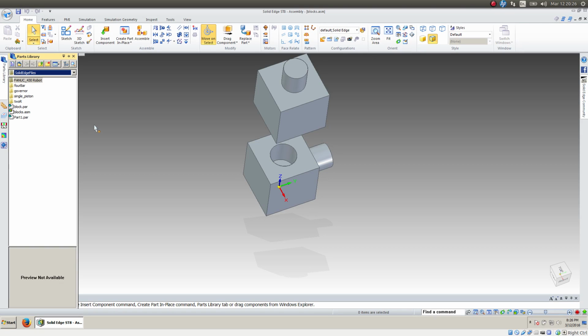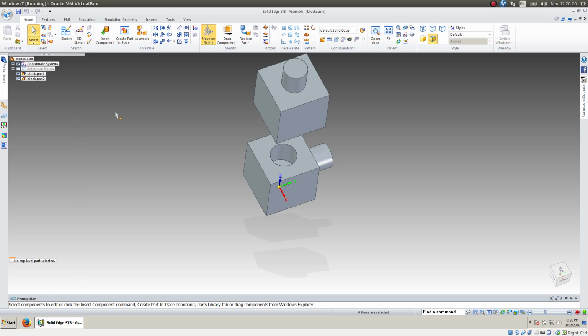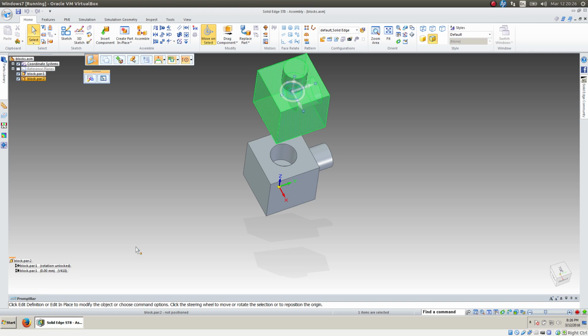In dynamic design or motion, it's possible to have somewhat adaptive inputs to forces and motions. In order to do that, it's necessary to use markers. We're going to look at this assembly where we have the two blocks, and the first block is grounded.